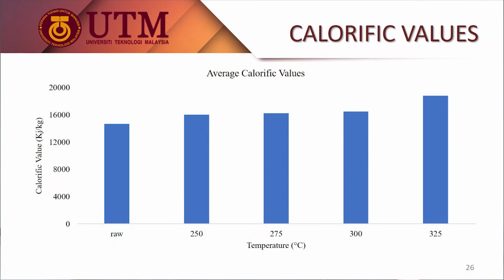For calorific value, the calorific value increases with an increase of torrefaction temperature. This is due to the increase in fixed carbon content after the sample has been treated with high torrefaction temperature. The torrefaction improves the calorific value by approximately 28%.